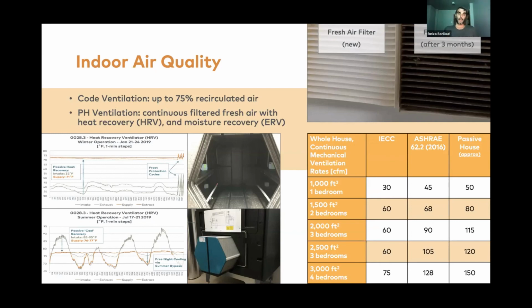In the summertime, this is also super efficient because, as shown on the left bottom side of the graph, you have a night cooling potential with the HRV bypassing the heat recovery core, providing free night cooling. So these units are extremely energy efficient, although the main purpose of passive house ventilation is to deliver indoor air quality.